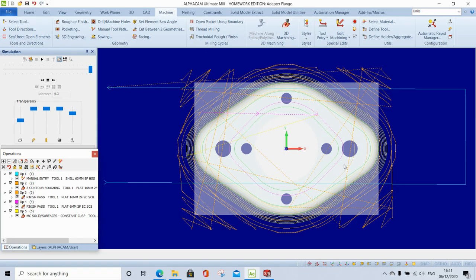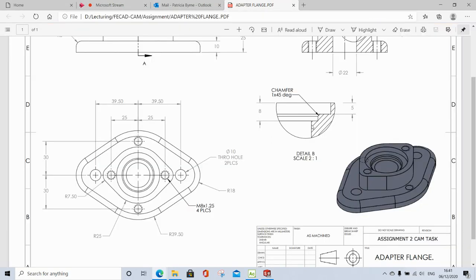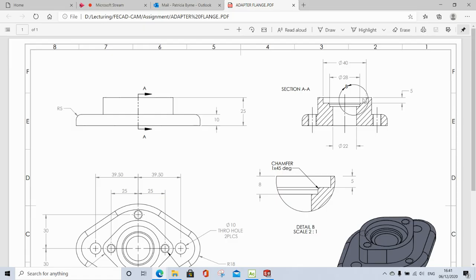Then you're going to be able to apply spot drill, then you'll go in, pack drill the full size, and then these 4 have to be tapped. Then you have your pocketing, and at the very end you can do the chamfer on the little area within the pocket. So if I go to this, okay, so you have your chamfer in here.